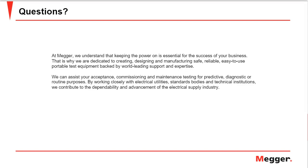One, it will affect the protection of the transformer itself by increasing the transformer magnetizing inrush, but again, the protection systems that protect transformers are typically protected against something like that, because the transformer protection elements are designed to take into account the fact that during energization, the transformer has a huge current inrush, and therefore these protection elements are kind of already hardened against this type of event.